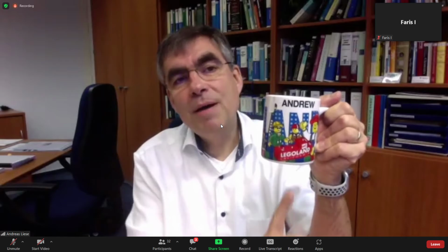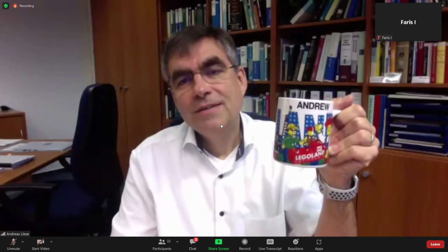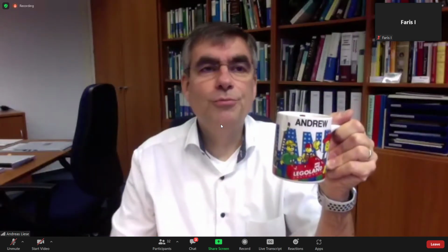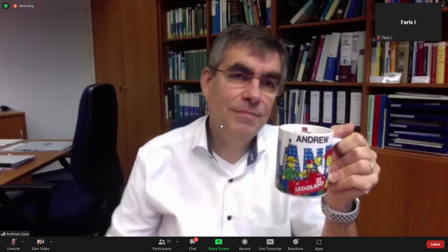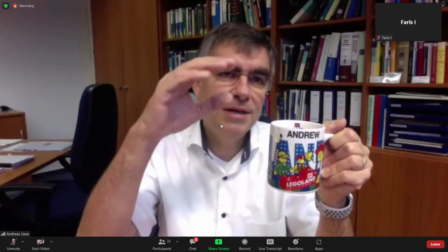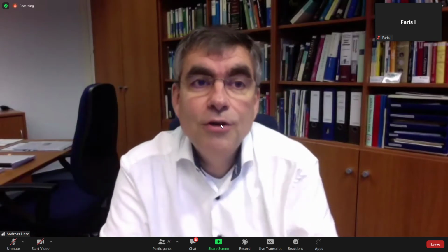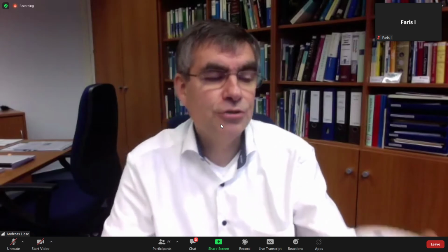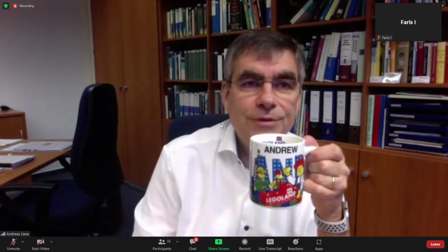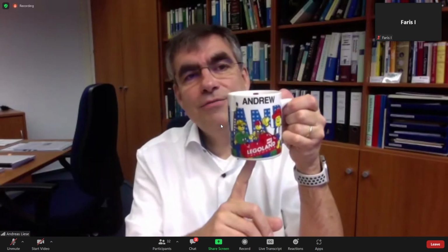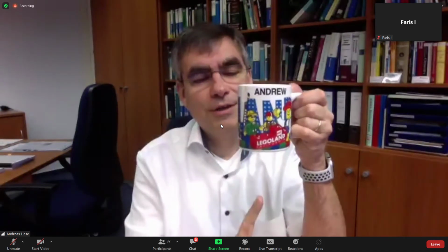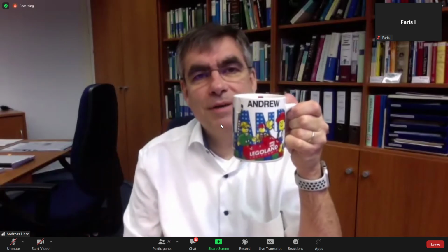Now, if we pump into this reactor, the force that we need to move the liquid through this packed bed will be different if we have large particles or small particles. That is what we name pressure drop, because we need to invest a high force, a high pressure to pump the same flux through this packed bed, from inlet to outlet.